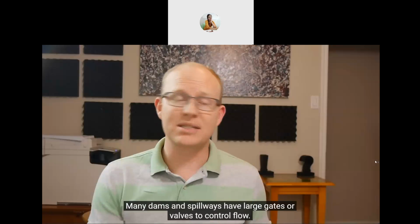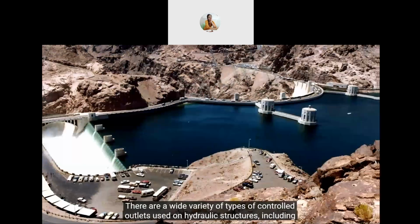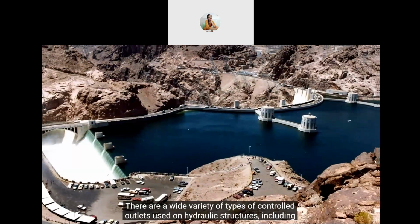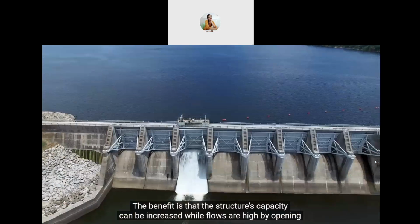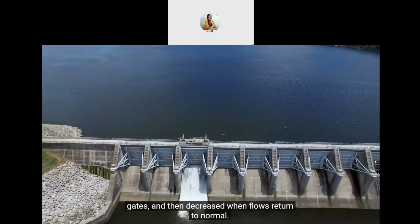Many dams and spillways have large gates or valves to control flow. There are a wide variety of types of controlled outlets used on hydraulic structures, including crest gates that act like weirs that can be raised or lowered. The benefit is that the structure's capacity can be increased while flows are high by opening gates, and then decreased when flows return back to normal.